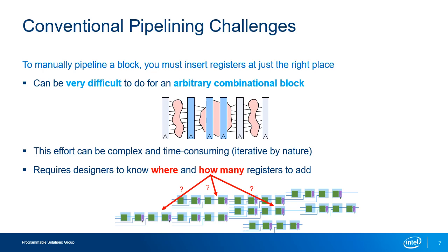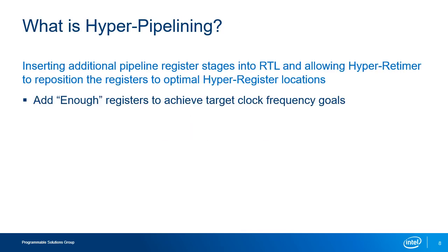Some designers write their code where they regularly code in multiple register stages throughout the logic. This style works very well in the FPGA, particularly with retiming. But invariably this may be hard to enforce in every logic module, as not all code is written by a single designer or team, and code that is reused from another project may not necessarily follow this rule. The answer to these challenges?